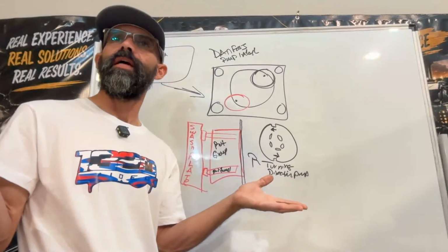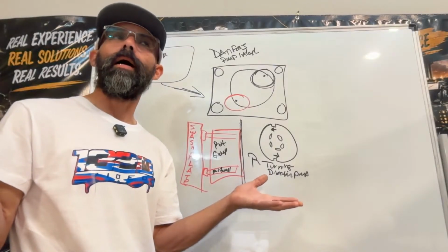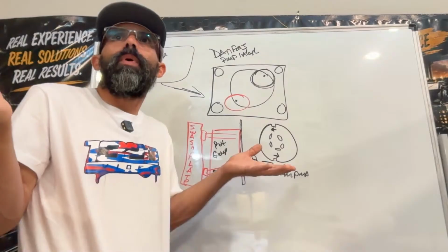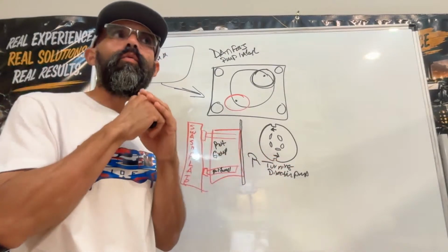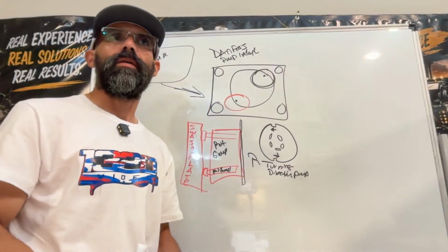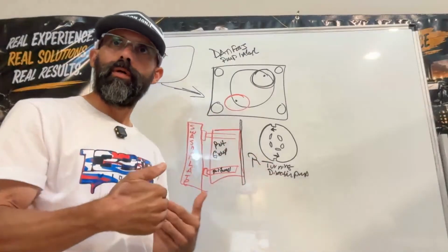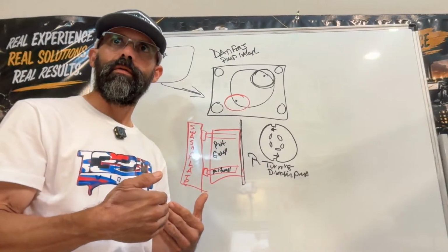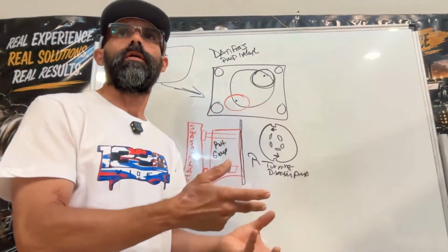Yeah, the pump might be damaged, but if I don't do that, I might miss why the pump failed. So basically, if I want to do a clean, thorough inspection, throughout my years of experience, what I do is remove the pump from the equipment, clean it completely on the outside, then start working on it.